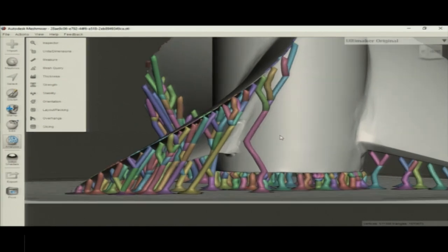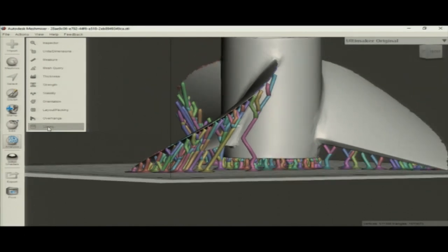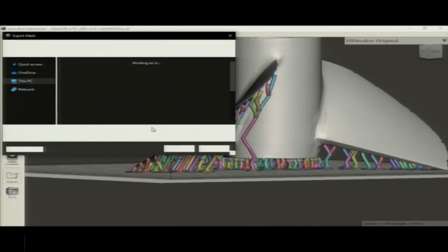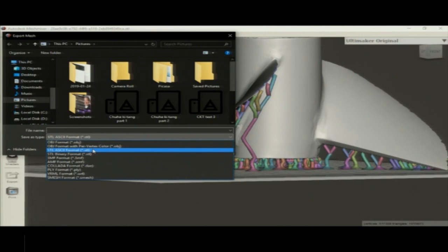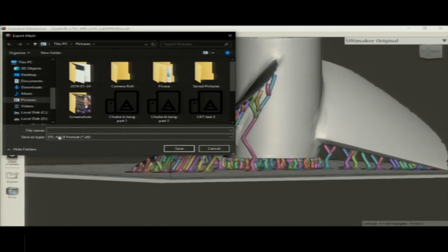There are so many options that could be discussed here, but in this small lecture I am just trying to discuss the support structure and small repairing part here only. So, we can do slicing here in Meshmixer itself, or we can export it to Repetier or different platforms. Then slicing we have already discussed. I am saving the component or the product into an STL file.